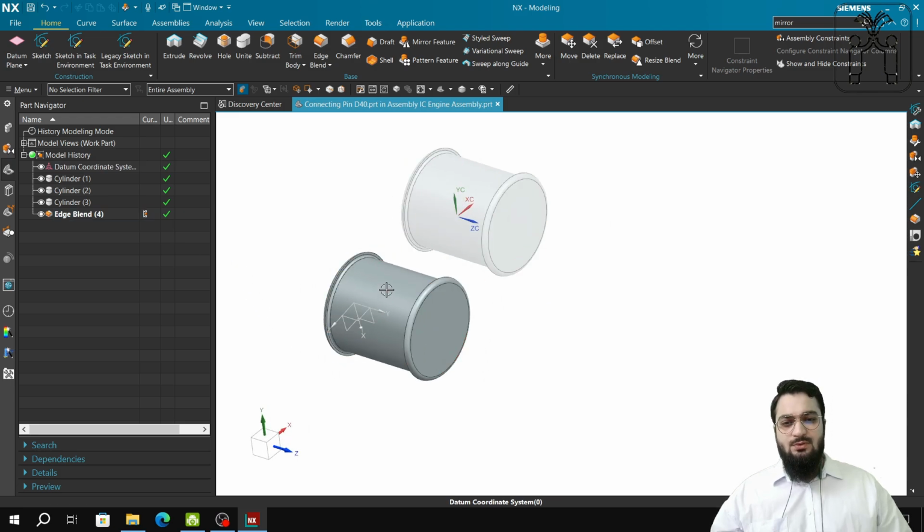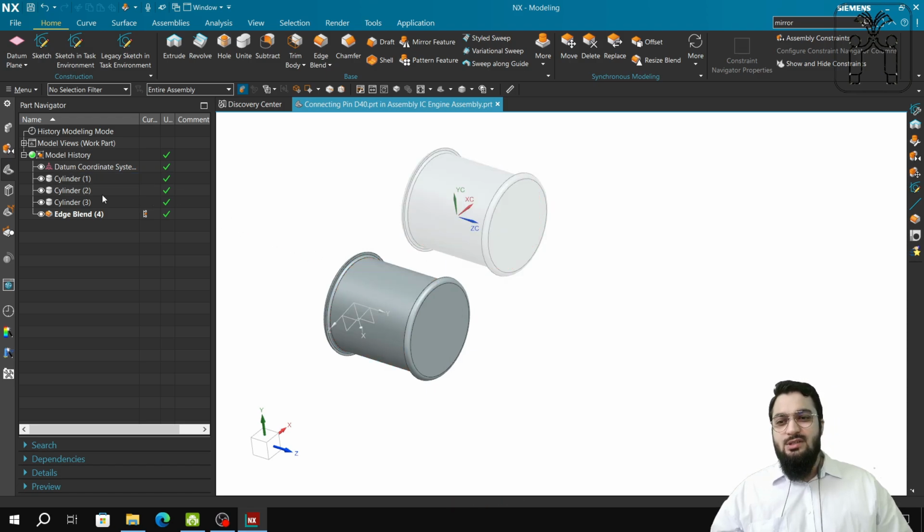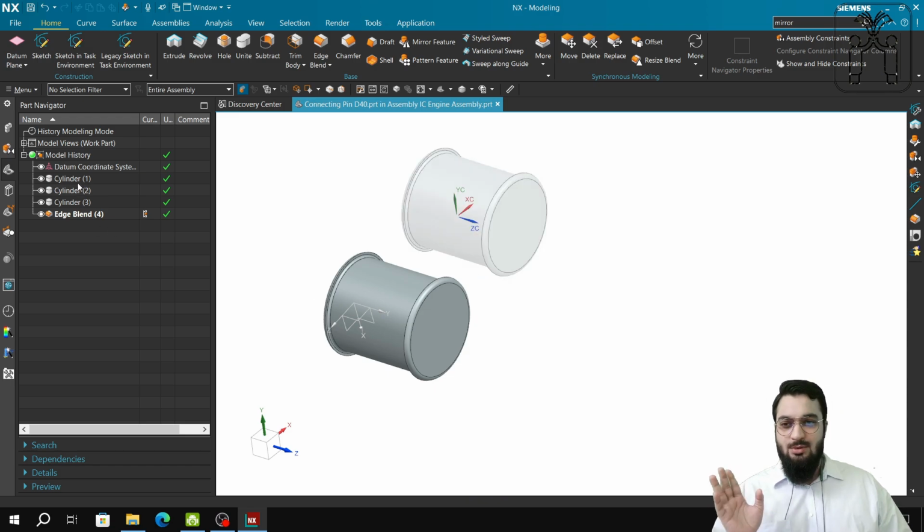First of all, the connecting pin is made only one time, but since it is used in 2 places, that is between the fixed pin and the crank, and second between the crank and the connecting rod at the larger diameter side, there are two connecting pins used. That is why we have added one connecting pin two times in the assembly.